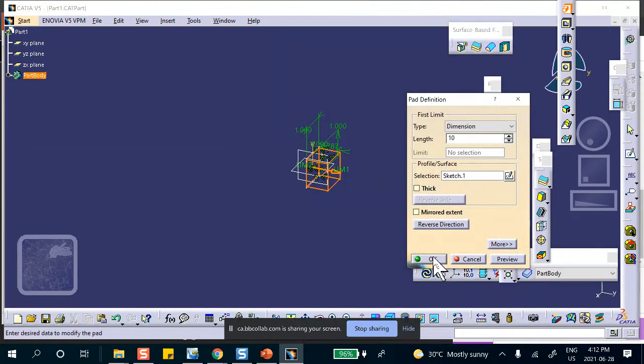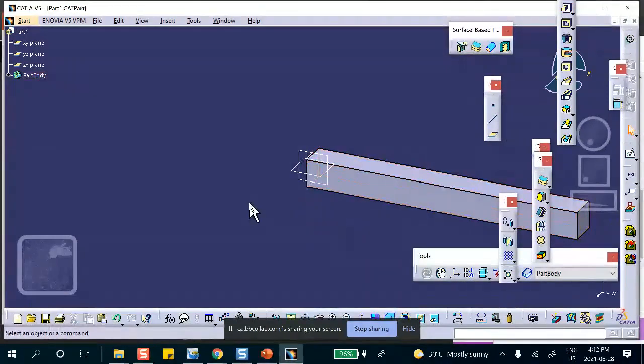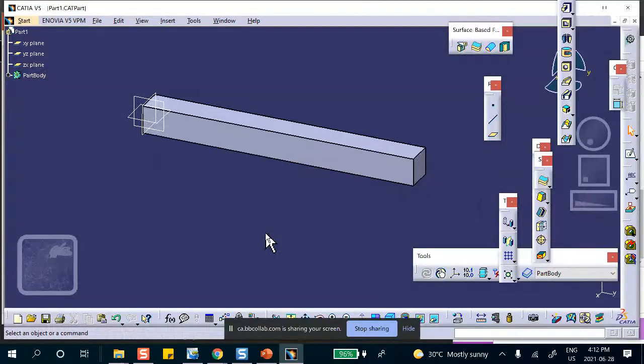Now, a couple of things. You already know that when it comes to buckling that we discussed last week, you still have homework to do. You should not use symmetry. You should not take symmetry into consideration, because if you take symmetry into consideration, you may skip certain loads which are lower than what you predict, and in fact, it can buckle out of plane, for example. The same thing with natural frequency.